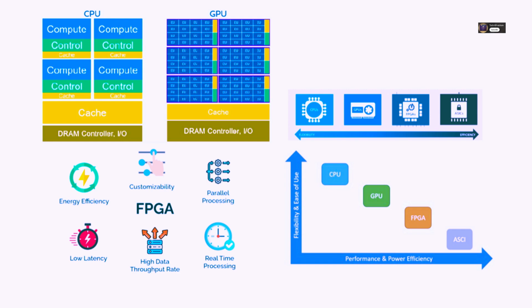So the final step, once specific algorithms like Bitcoin's SHA-256 became totally dominant and stable, was the move to ASICs. Purpose-built mining ASICs sacrificed all flexibility but offered the absolute maximum hash rate per watt. Non-negotiable optimization became the only way to stay competitive. That journey perfectly shows the progression. Trading flexibility for efficiency as requirements solidified and scale increased.